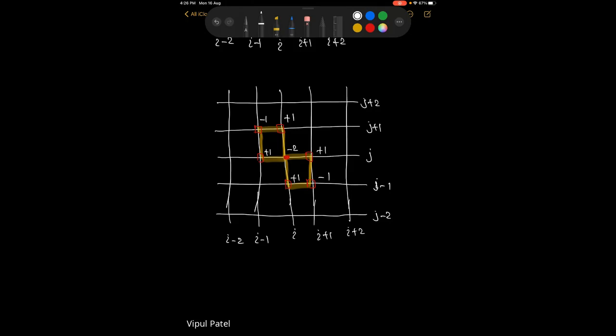If the node at phi ij has the highest weightage in your formula, then your convergence becomes very stable. Then you can use your Gauss Seidel method or something like that. Sometimes you have to derive a similar expression.